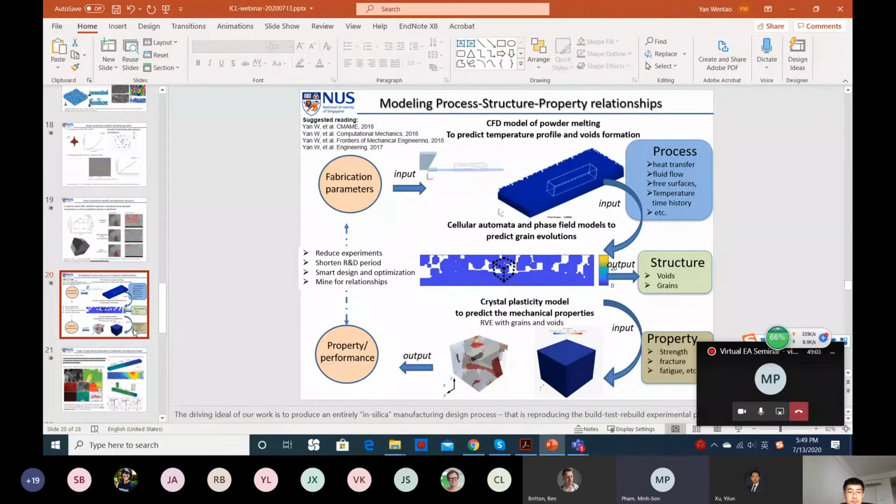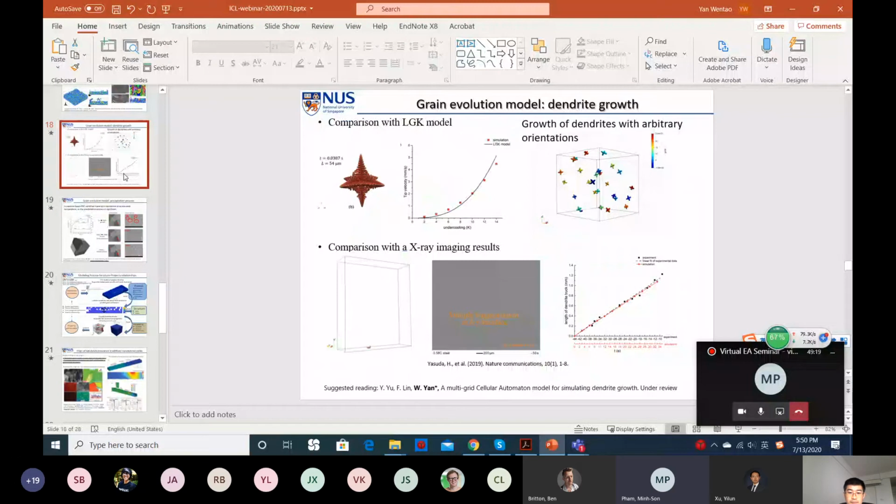If you want to predict the microstructure, did you verify the grain growth with experimental observation, for example EBSD data? I know you verified the dendrite spacing already, but have you done that in either laser beam or electron beam melting, to verify your prediction of the dimension of the dendrites or cells, to see whether they are in good agreement with the experimental observation?